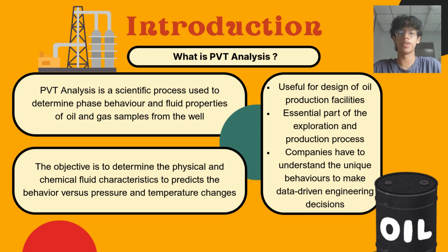So, what is PVT analysis? PVT analysis is a scientific process used to determine phase behavior and fluid properties of oil and gas samples from the well. The objective is to determine the physical and chemical fluid characteristics to predict the behavior versus pressure and temperature changes.